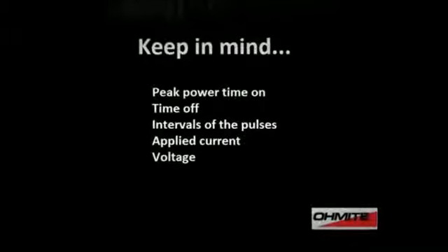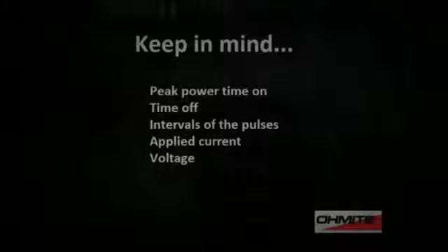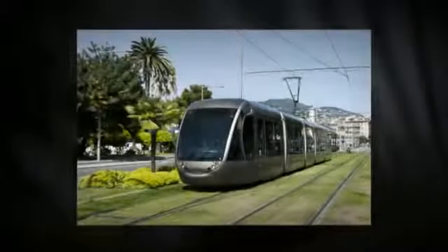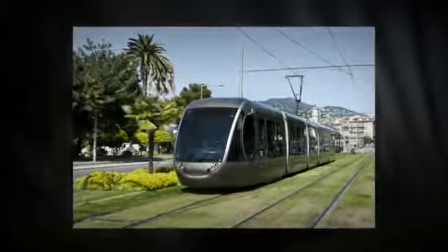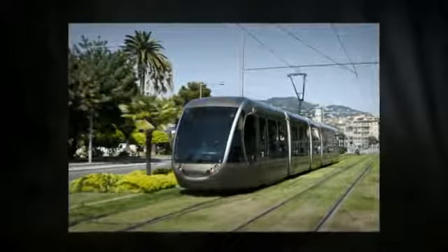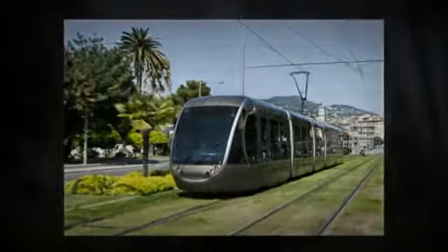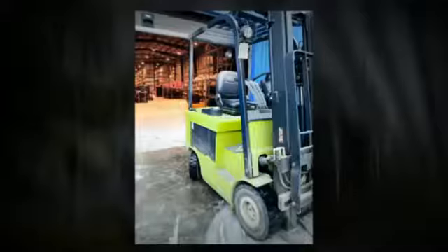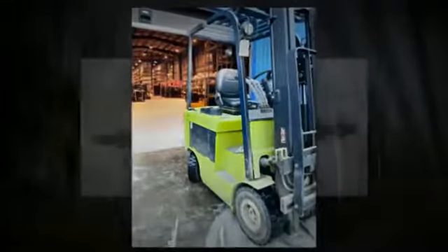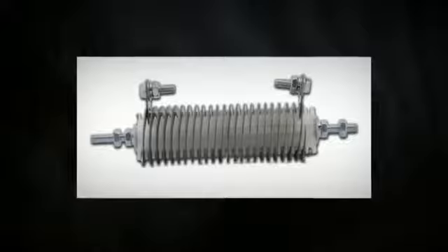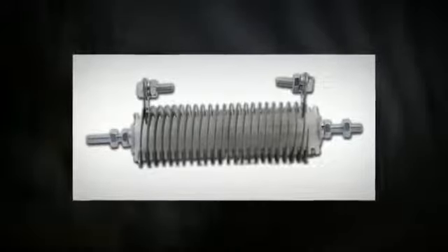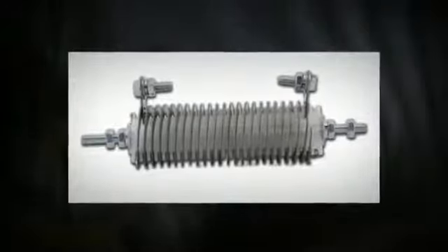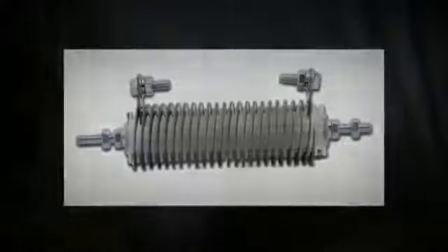Ideally, you calculate the mechanical energy involved in each stop, which will be the sum of the kinetic, rotational, and potential energies, less any friction losses, if significant, and less the electrical losses in the motor system. Knowing the stop energy and the duty cycle, you can calculate the average power into the resistor, which for most duty cycles will be the right power to begin testing. When the stop time is short, you may need to consider a resistor with a larger thermal capacity to prevent overheating. To calculate the maximum dynamic brake resistance value of a small motor, follow these steps.